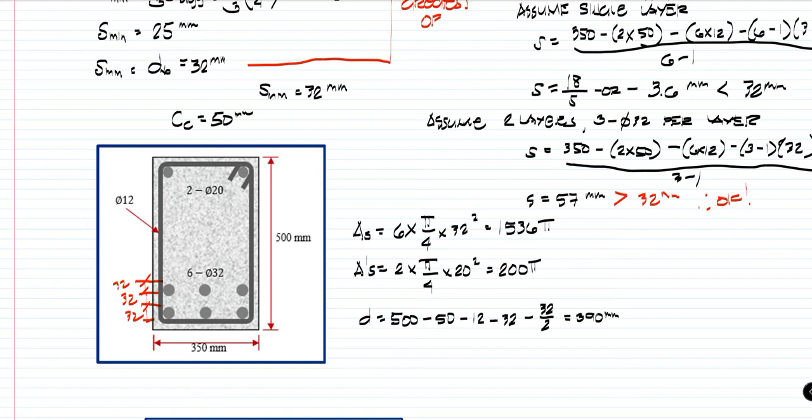Now, let's proceed dun sa concrete cover nung compression reinforcement, which is D prime. So, that will be 50 plus 12 plus kalahati ng bar niya, which is 20 over 2. So, para lang natin inadd yung clear cover, yung stirrups, at yung kalahati nung diameter ng bar. So, that will be a value 72 mm.